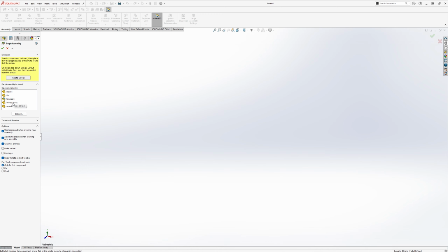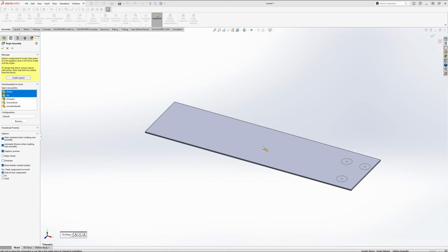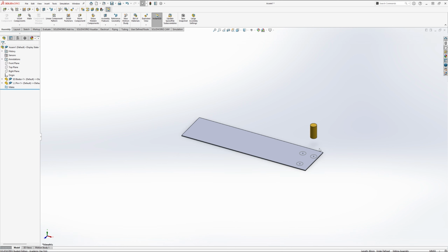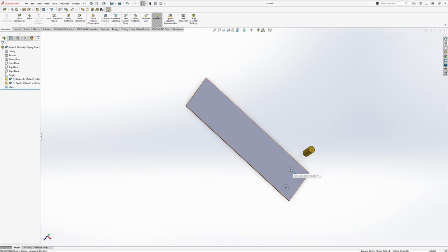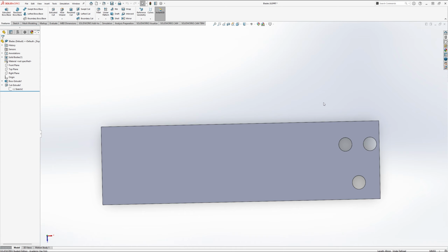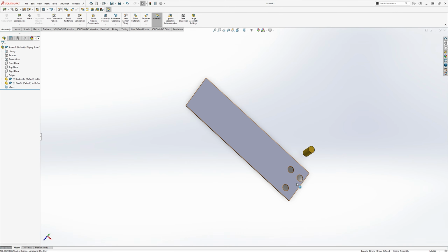So I'm going to close this one block later, but basically we want the blades and pin. So let's just place a blade here, pin here, and as you can see, that's really weird. It hasn't extruded that out. So we're going to go back into our blade, make sure that it is extruded, make sure you save, and go back to our assembly, and there you go, we have our extruded blade here. We have a pin there.